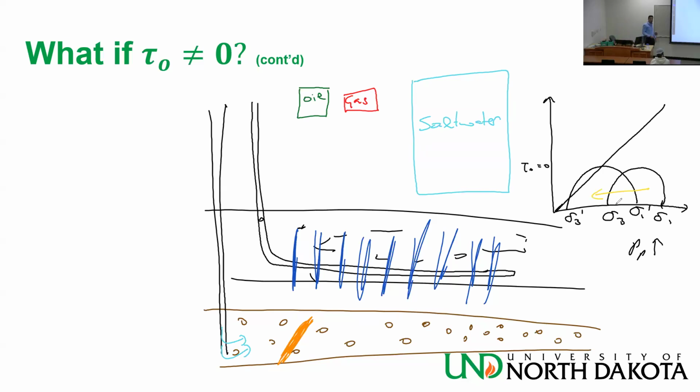So can we know if that failure is shear or tensile? It's shear 100%. Now how can we know from only the diagram? Because the Mohr-Coulomb is for shear failure. But you can use it for tensile failure too. But the Mohr circle is for shear failure, because remember what you have on the y-axis is the shear stress.